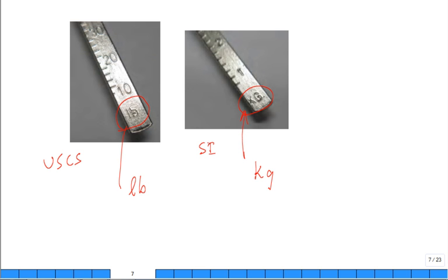Well, that's LB, so it looks like 10 pounds, 20 pounds, 30 pounds. Pressure in pounds? Well, they didn't have enough room to put PSI, so they just put LB. But if you go in there, it's kind of slang. You got to know the slang, right? Somebody says, how much pressure do you want in your tires? Oh, put in 30 pounds. What does that mean? They want 30 PSI. 30 PSI. Okay, so that's what that means.